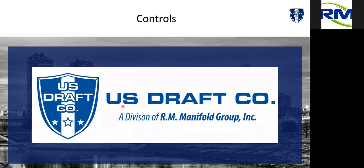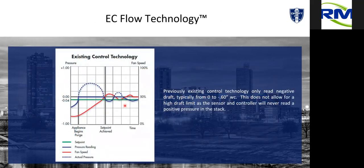So we've talked about the fans and we've talked about the dampers, and we feel like we're definitely leading the industry in some of the things that we're doing. But where we feel we are next level is in our controls. The industry standard for years and years has been a negative pressure controller, typically from 0 to 0.6 negative pressure. That's the range that controller can read and control in. What happens is, we talked about the pre-purge of that appliance, that pressure will spike during pre-purge, and the controller stops at 0. It's kind of like old speedometers that stopped at 85.